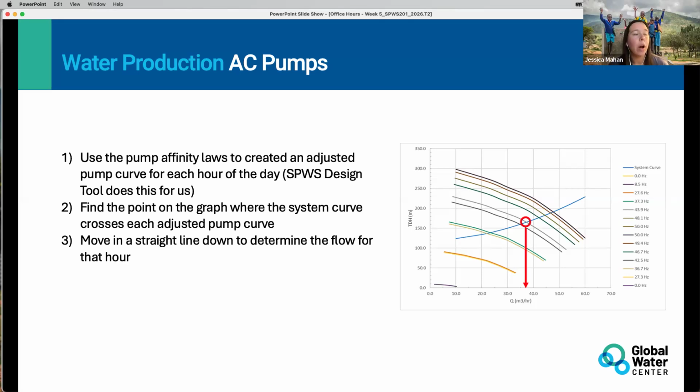So we're not operating at what we might consider a full power state. We are running at an adjusted power because we just don't have as much from the solar array. And so that's where we use affinity laws, and we can calculate the flow rate and the head at lower power based on what our full power curve says.